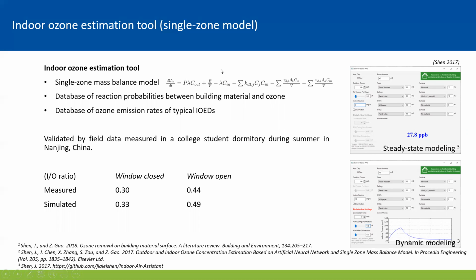So we developed this estimation tool for indoor ozone concentration. It can calculate both steady-state and dynamic modeling for indoor ozone concentration. And this tool was validated by the field data measured in a college dormitory.